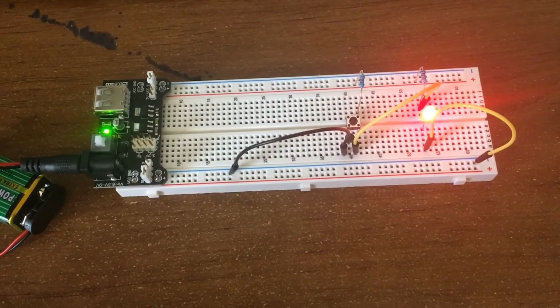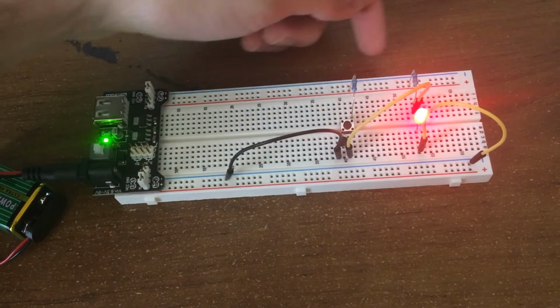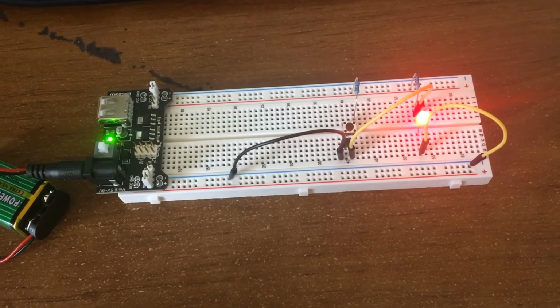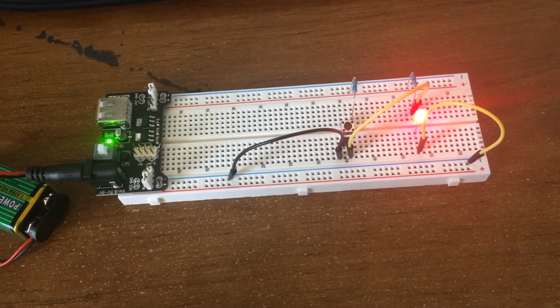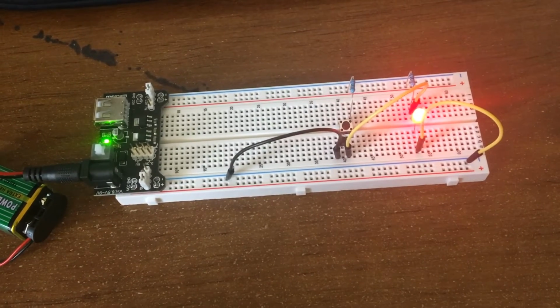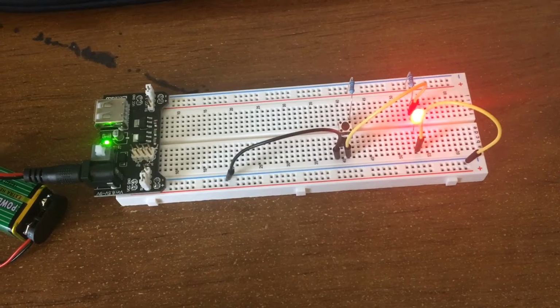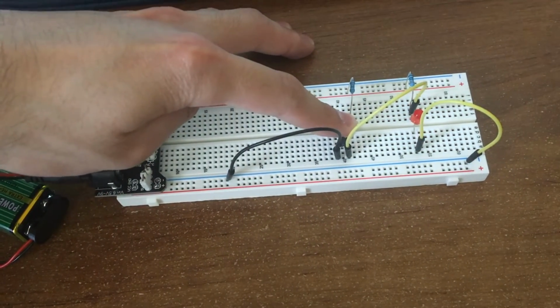Now we're going to test our NOT logic gate. Our truth table says that there's only one input, which is A, and one output, which is C. Our first case, it's when A is 0 and C is equal to 1, meaning that if I'm not pressing anything, the LED should be turning on, which it is. And our second case is when A is 1, meaning that C is equal to 0. As you could see, I'm pressing A and our LED is off, which it is.